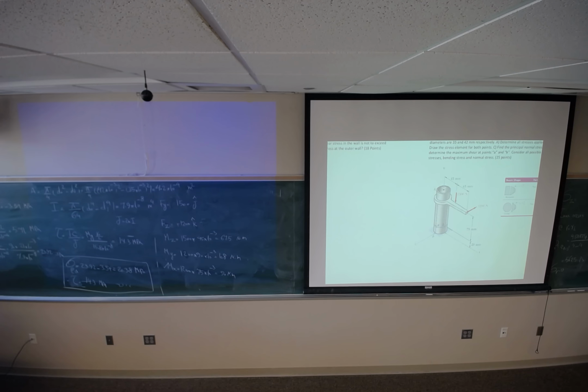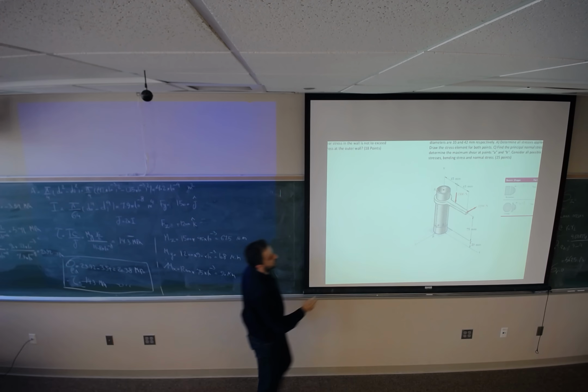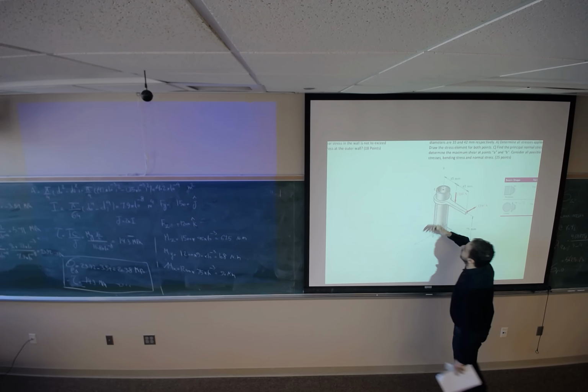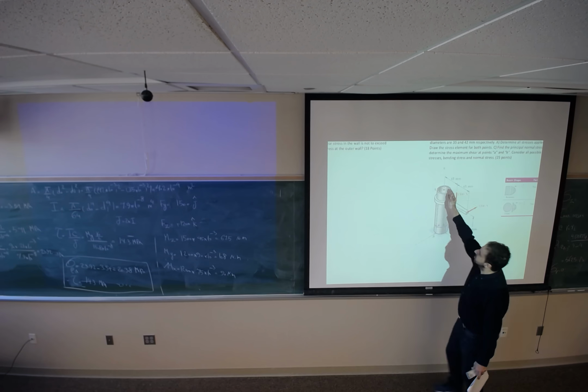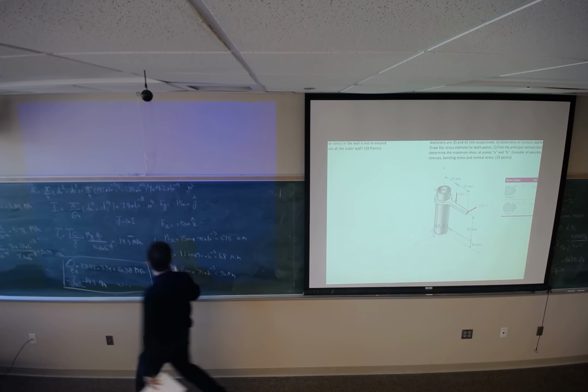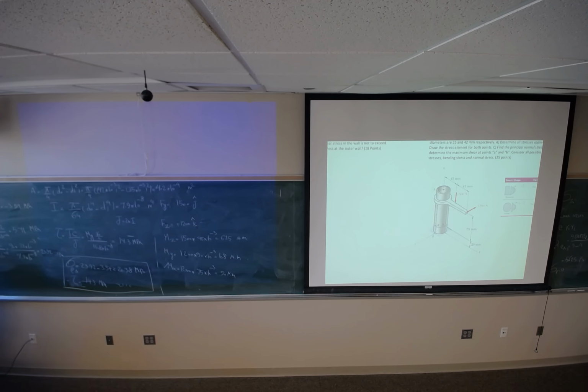For bending moment, MX doesn't make any normal stress because it's gonna be located on neutral axis, point P, but MZ does. So 90 is gonna change to MZ, which is 67.5.